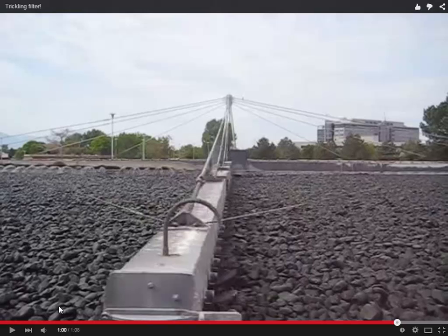Okay. Yep, part of it is that, remember, in secondary treatment, the bacteria need the substrate, and what we're spraying on the bacteria and the rocks that the bacteria are living on is water that's already been through primary treatment, so much of the suspended BOD has already been settled out, but the dissolved BOD is still in the liquid.